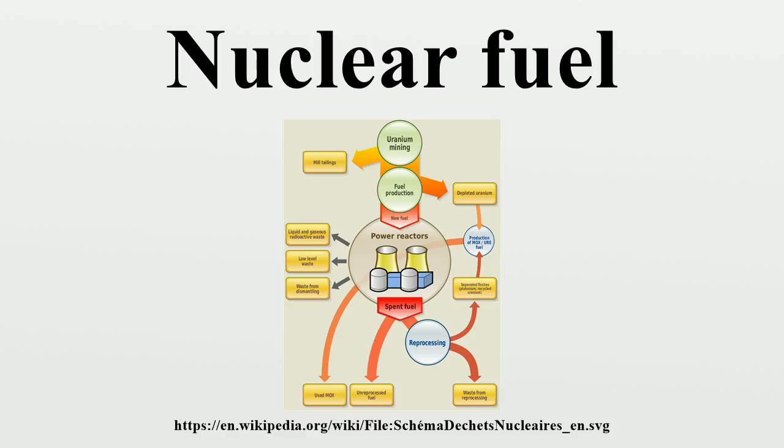Ceramic fuels. Ceramic fuels other than oxides have the advantage of high heat conductivities and melting points, but they are more prone to swelling than oxide fuels and are not understood as well. Uranium nitride. This is often the fuel of choice for reactor designs that NASA produces. One advantage is that UN has a better thermal conductivity than UO2. Uranium nitride has a very high melting point.